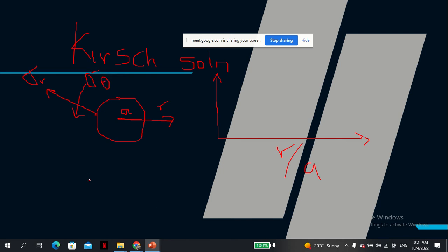They are what we call the principal stresses in this element or in the soil. There are principal stresses which are sigma 1 and sigma 3, as you know. So this would probably be sigma 1, and if you remember your Mohr circle, sigma 3. But in this context, these are usually called P1 and P2 from the analysis of the Kirsch solution.